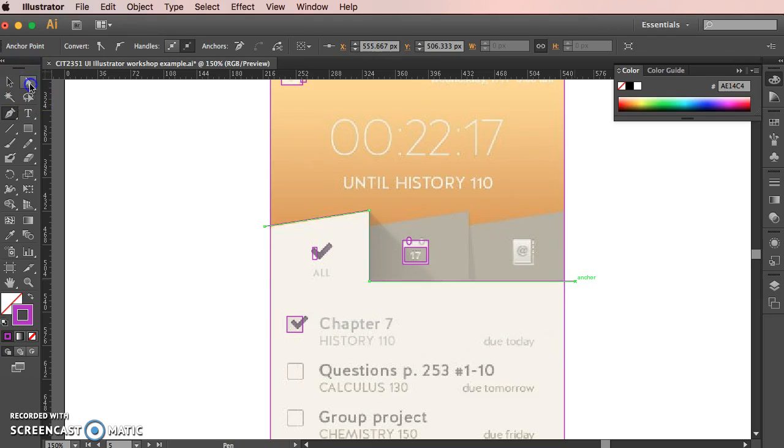Okay. If you don't use Shift, then what you can do is select the 2 individual points with the white arrow and use the Align tool to make sure that they're perfectly aligned. I can also use the white arrow, not the black arrow. It's called the Direct Selection tool. It allows me basically to select individual or multiple points, but not the whole object. The black arrow would select this entire line. The white arrow allows me, for example, just to select this endpoint, and then I can move just that one. So if I didn't get the angle quite right, I can adjust it. Likewise over here, I could go down, but I feel it was about right. So I'm going to put it back.